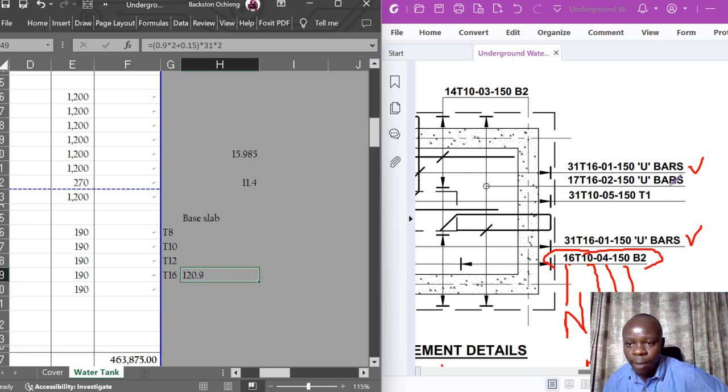Bar mark number 2 is here. Okay, it's also another U, and as per the explanation which I gave, follow that particular line. This is the line that is below the marking. Follow it all through. When you reach here, you will find another arrow, like in this case. So this arrow is just a demarcation or annotation arrow, but it's not the reinforcement bar itself.